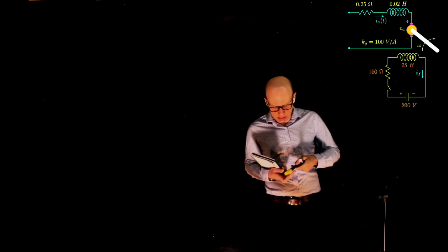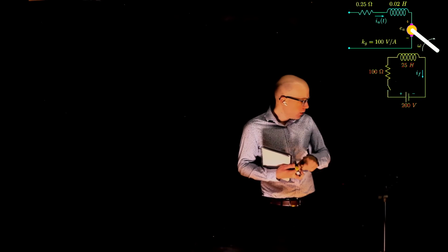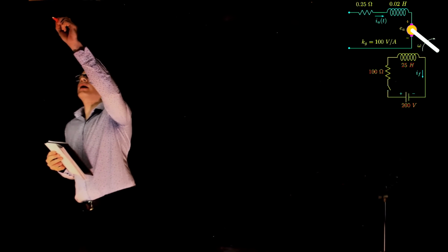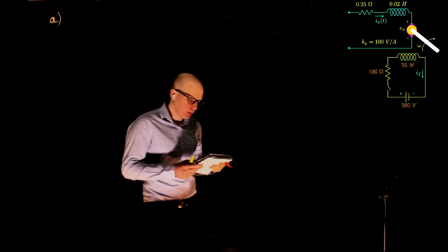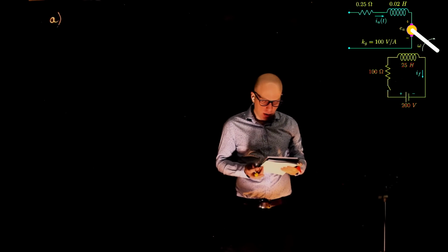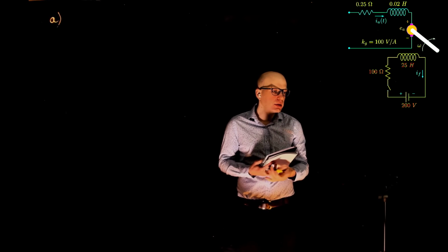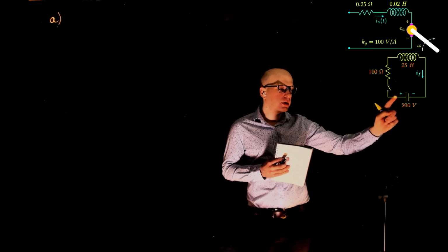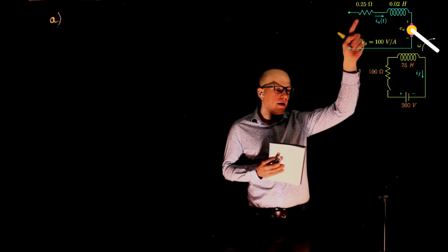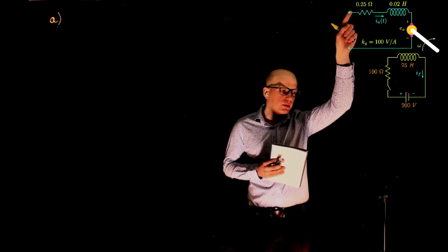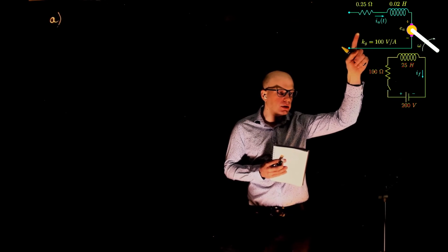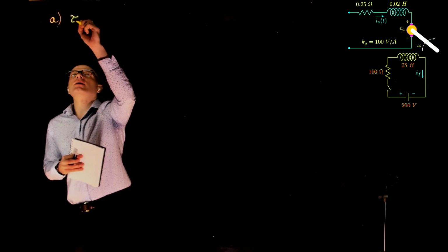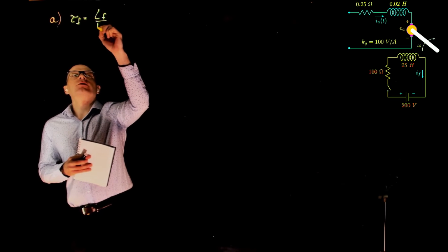So let's do this example then. To start with A. And in A, we want to know the equation for the EMF as a function of time. So we can start by calculating the time constant. And because we're dealing with this part of the system just for EA, for now, this part can be neglected. Of course, the circuit is open, so there is no current developed here. The only time constant is this one, and we call that tau F, which is LF over RF.